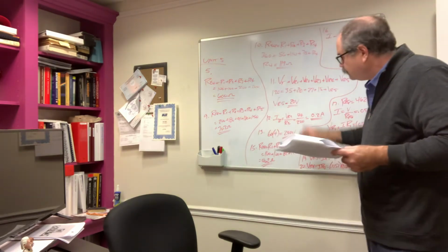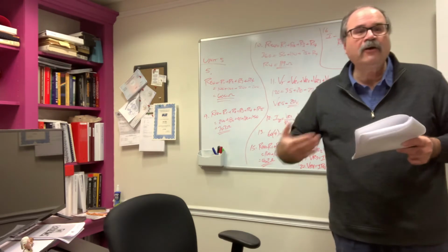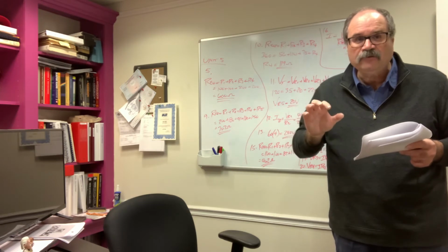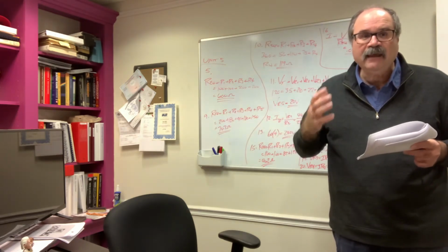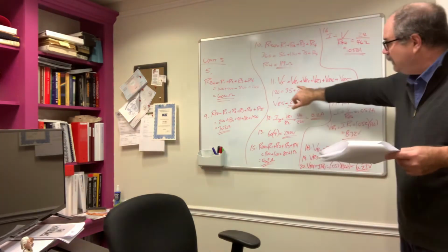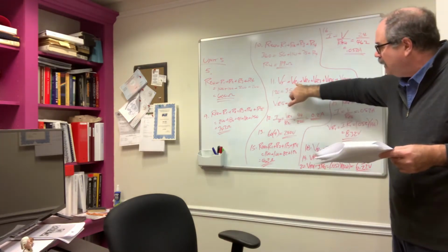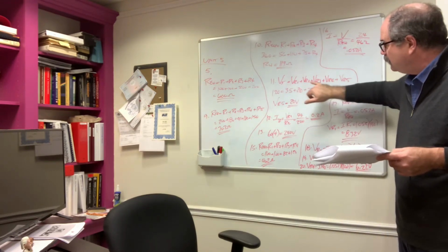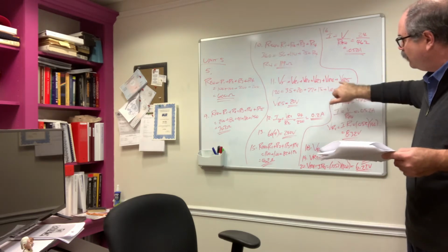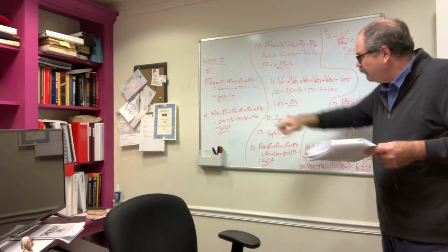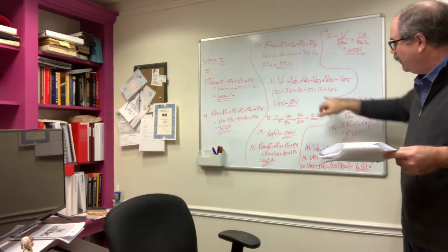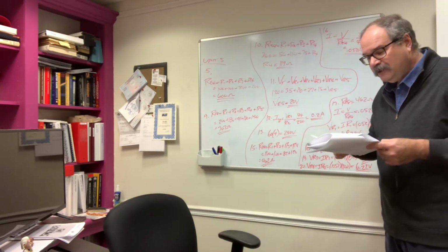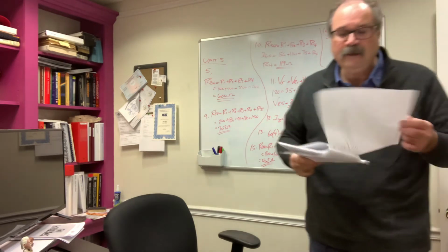So remember, in a series electrical circuit, the current remains the same through each of the resistors, but the sum of the voltage drops across each resistor has to add up algebraically to equal the source or the battery voltage. So we designate that total voltage V sub t is equal to VR1, meaning the voltage drop across R1, plus VR2 plus VR3 plus VR4 plus VR5. Total voltage for the system was given as 120. We plug the rest of the values in and solve for the voltage across that 5th resistor. So the voltage drop across the 5th resistor should be 20 volts.